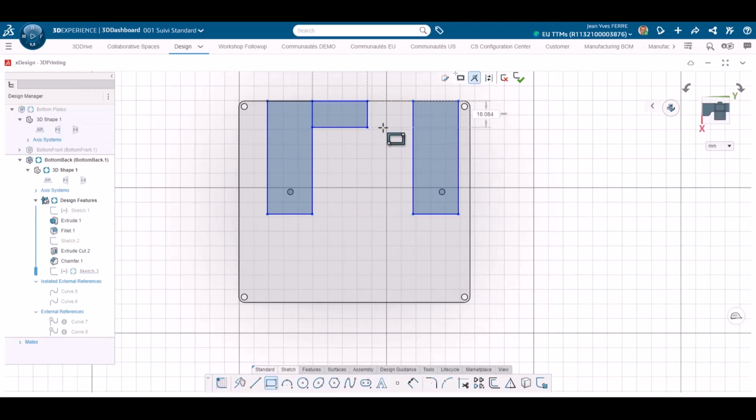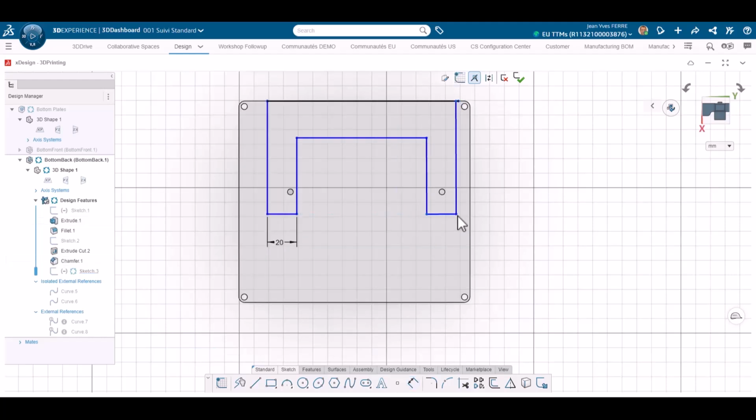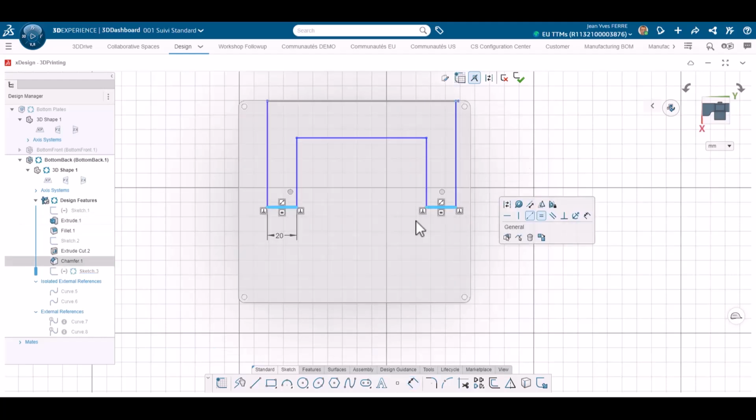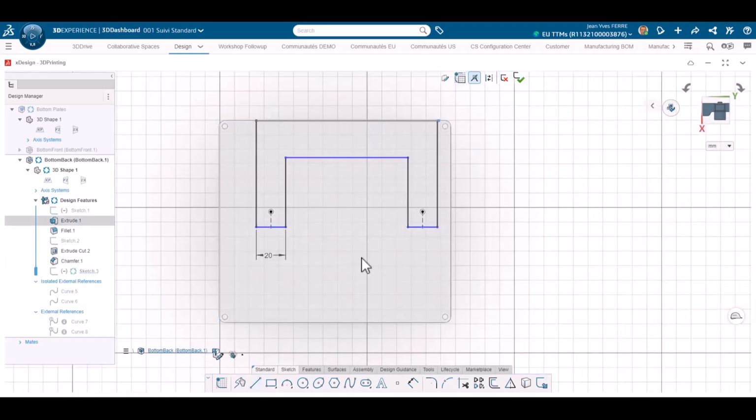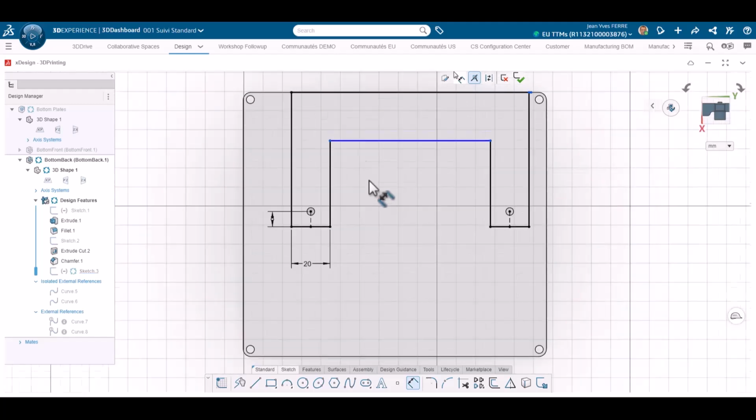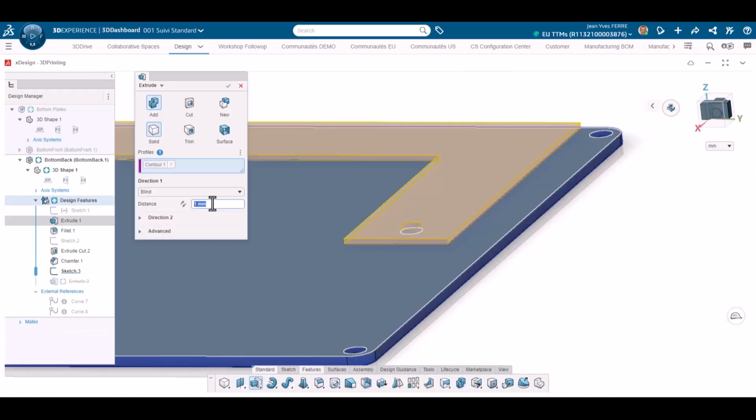I will start with some changes on one part to add thickness where the drawers are attached on the plate. To do that, I create a sketch with several rectangles. I trim entities, add a couple of dimensions. I check the sketch degrees of freedom by moving a corner. Some adjustments are needed when you trim, because relations may disappear with the entities you just trimmed.